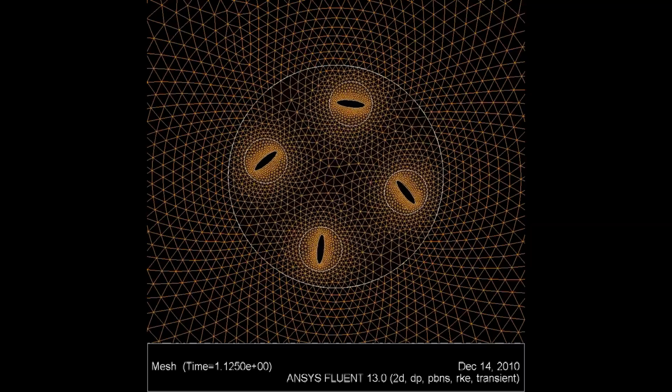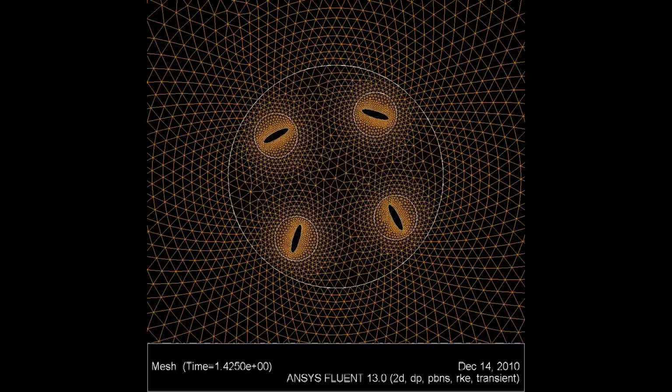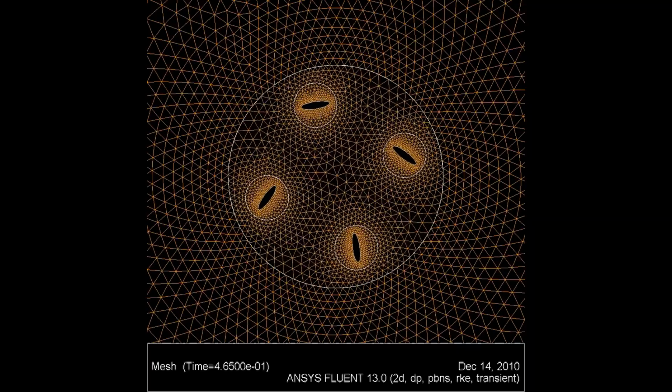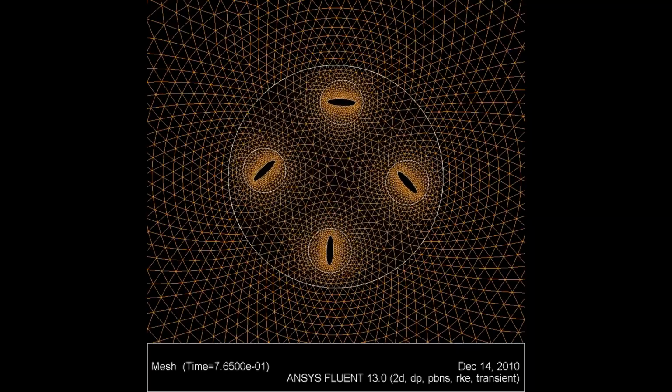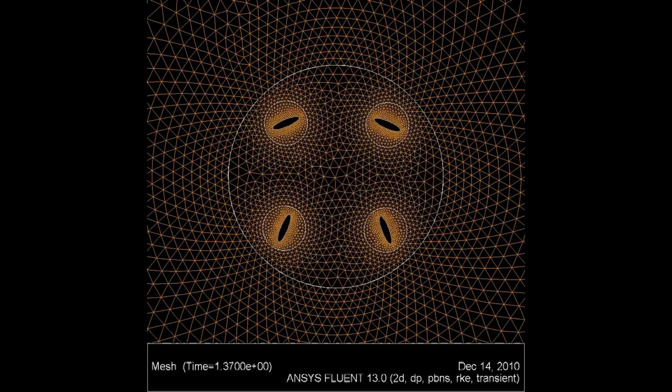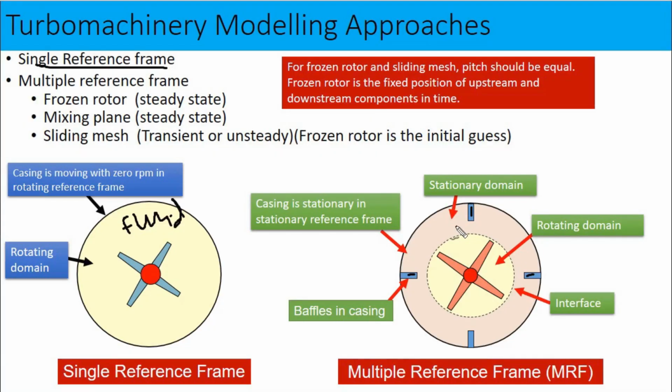In this project, we are going to simulate the rotation of a vertical axis wind turbine, VAWT, using 2 different approaches available in ANSYS Fluent, each suited for different levels of accuracy and computational cost. In the first part, we will simulate the rotating blades using the MRF, moving reference frame, approach.